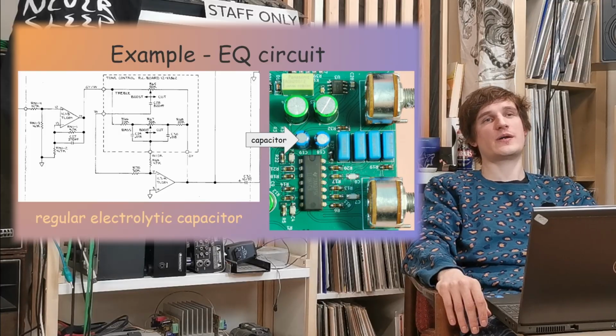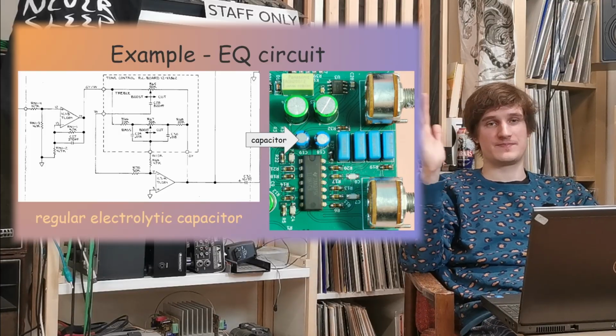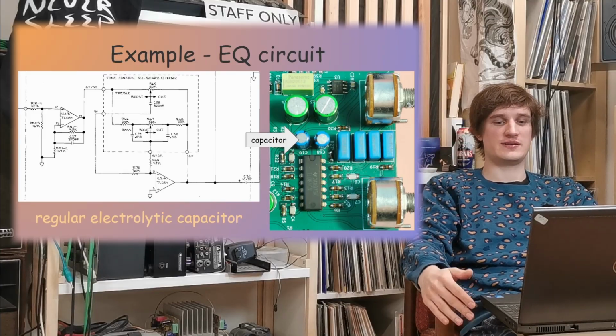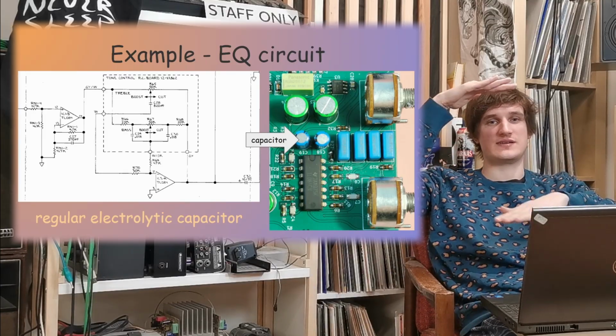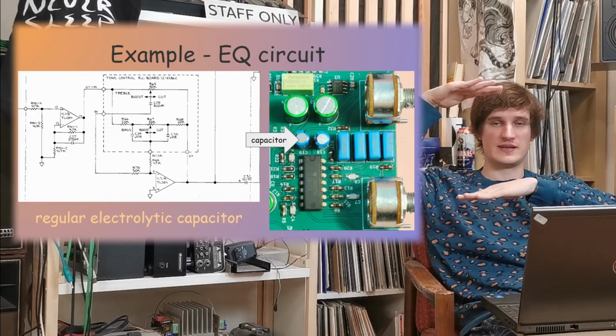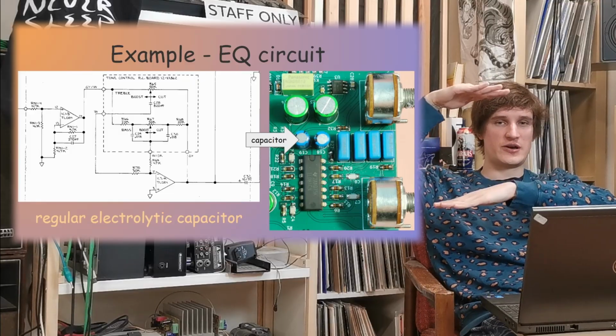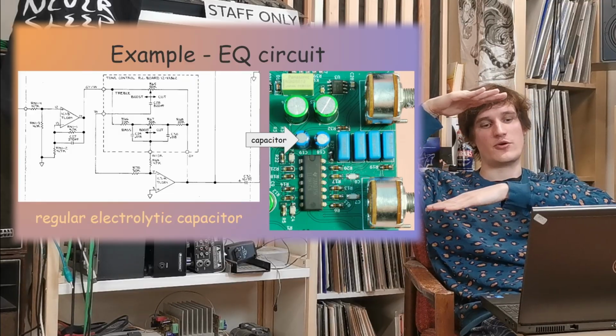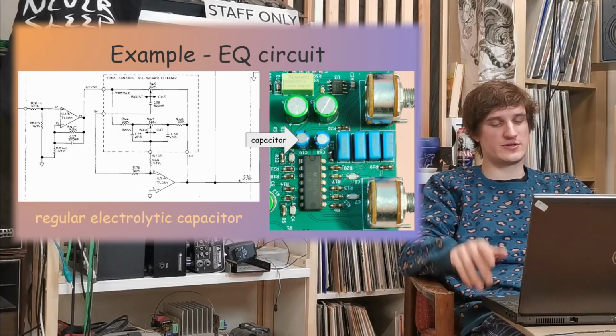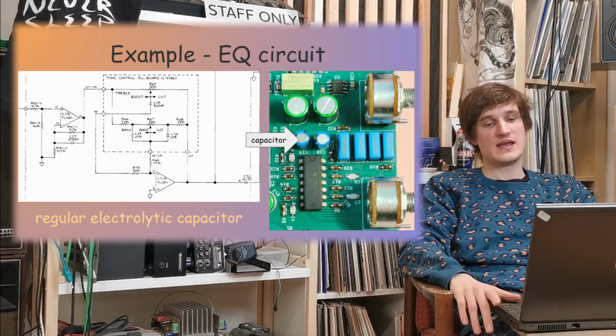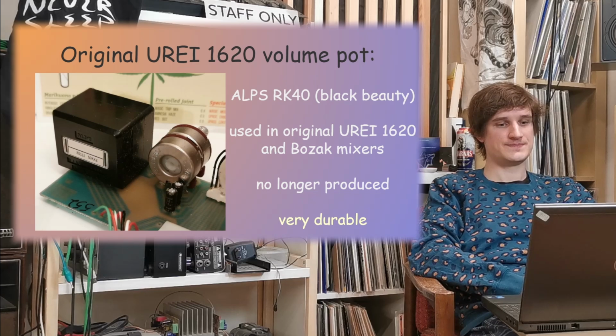Here we don't have to care about this symmetry I told you about, because this capacitor is just across the power rails, so it's constantly polarized by one of the power rails. So a regular electrolytic here in this application is perfectly fine.